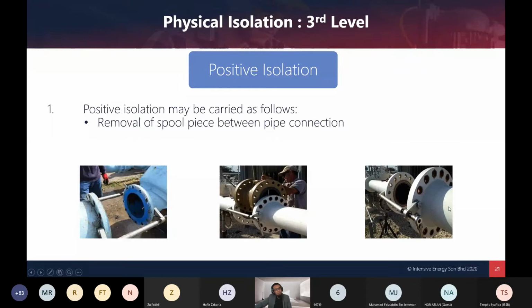Let's say people are working on downstream of the equipment, isolation, and then this valve ada, they cannot sit tightly lah. So gas boleh slip through or hazardous content boleh slip through, pass through. So instead of going to the people directly working there, they keluar pergi atmosphere lah. You dah control. You memang dah control dah. Before you pergi drop spool, you dah double block and bleed.